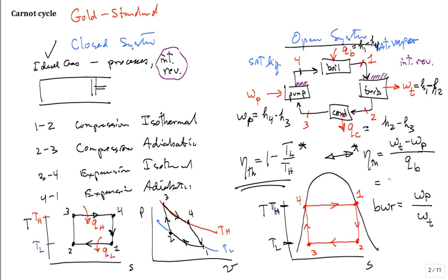All right. Some people will also see the thermal efficiency written this way. They'll see it as 1 minus Q condenser over Q boiler. What? How did that come about? How can that be true? Well, what did they do here? This is work net divided by Q of the boiler. True? Could I replace work net by Q net?